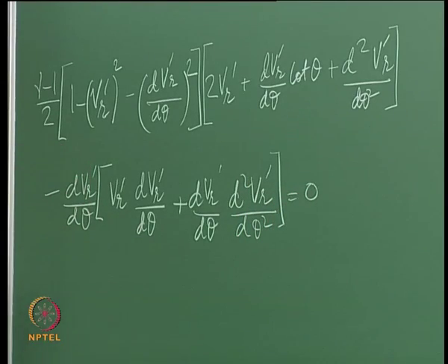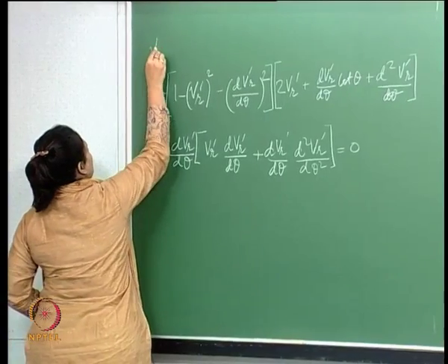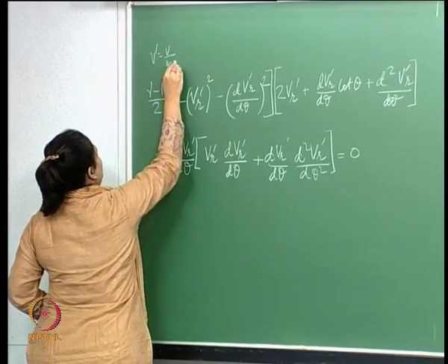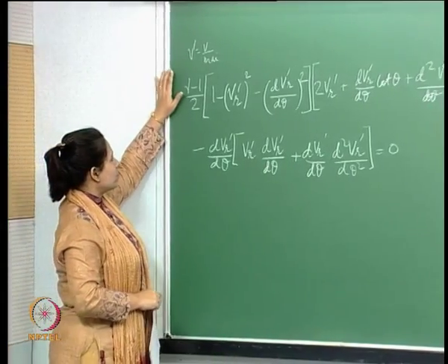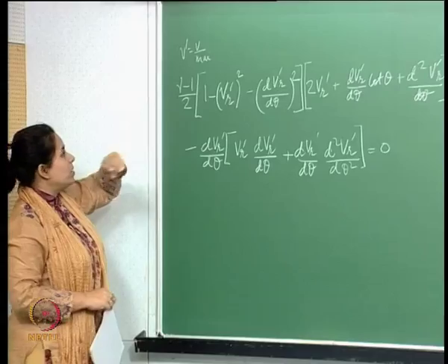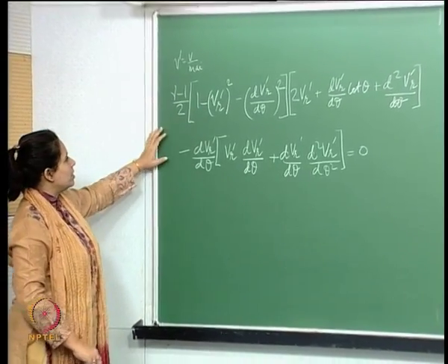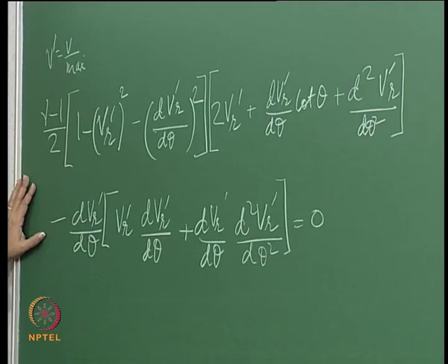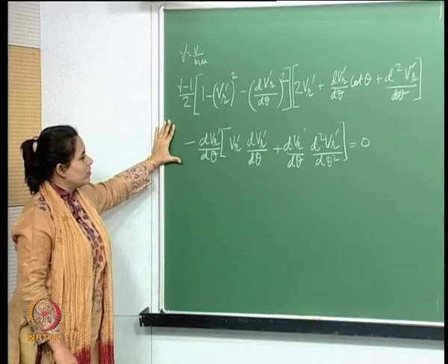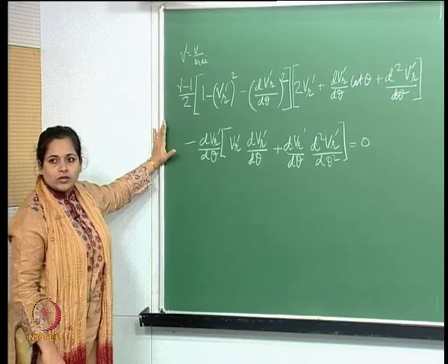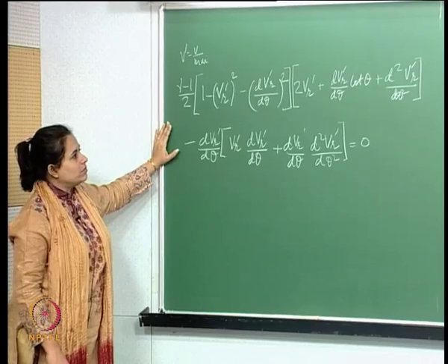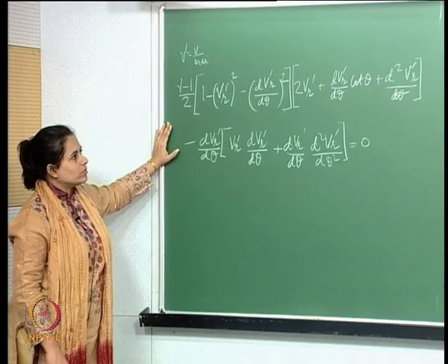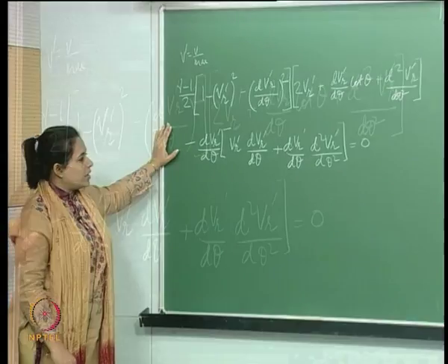So this was essentially equation 6. And if you remember, this was the unknown, the non-dimensionalized form, which is Vr dash here. This was our Taylor-Maccoll equation, which we needed to solve numerically. We can't solve this in closed form to get the solution for the flow past a cone.